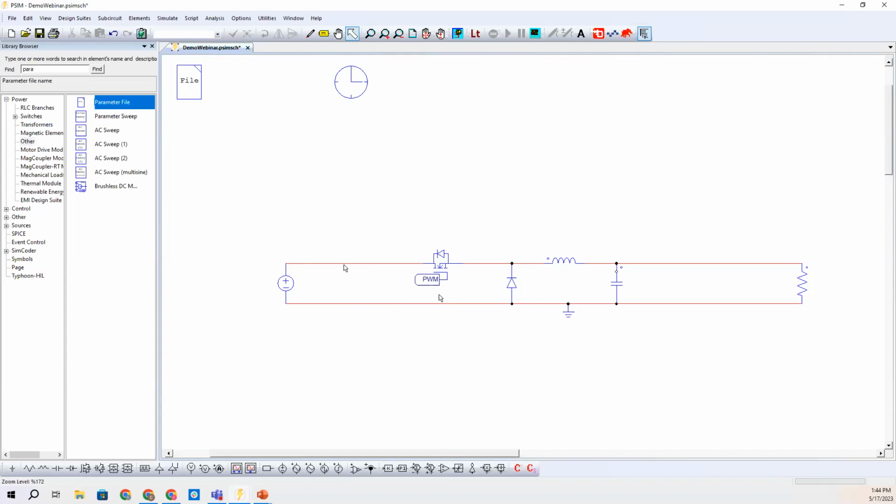And if I make this label anywhere else in our system, it's like a wireless connection. So we don't have to actually draw that wire. We could just cross over. But if you're anything like me, I don't like wires crossing over in a schematic, because if I don't realize there's not a black dot, or there is, I might think that they are connected when in fact they're just overlapped in the diagram. So I'm going to grab another label and I'll keep it PWM. So now we have our symbolic connection to our other PWM up here, and I'll place it right there.